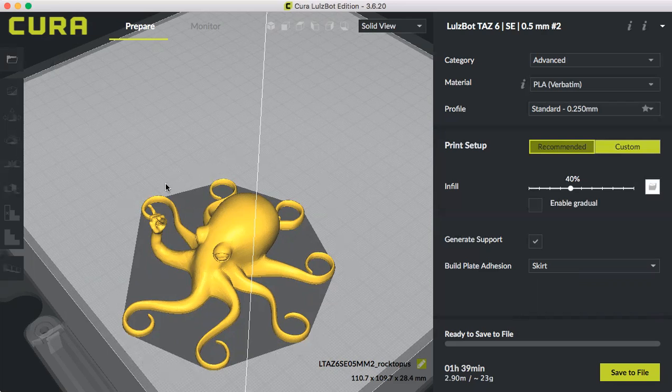If the filament is kind of old or something's funny with it, it'll print through that bad section right at the beginning and straighten itself out as it goes around. Then once it gets to your print, it's all warmed up and ready to go. And if you're watching the skirt and notice that it's not printing correctly, that's a good indicator to change your filament or make an adjustment somewhere else.